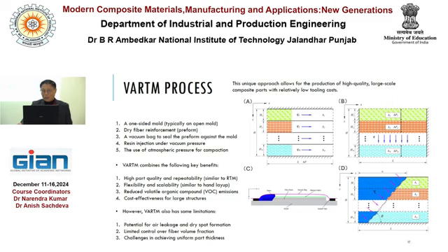During the heat treatment process, the resin will shrink. That means the final dimension is not possible to estimate in advance. So after trying to manufacture practically, they can know how much the product will shrink. So by trial and error, they can get the accurate final dimension.